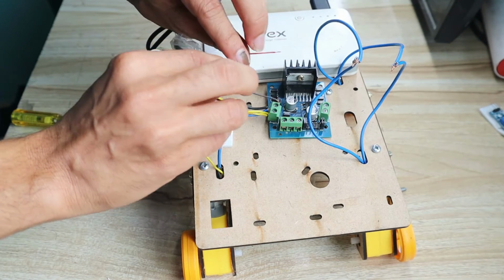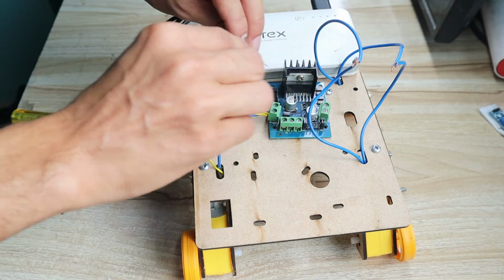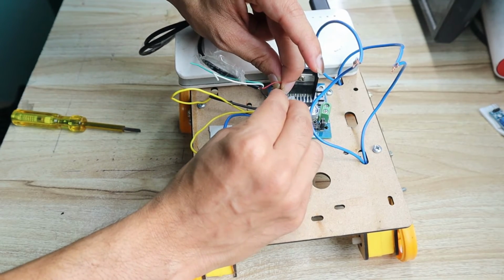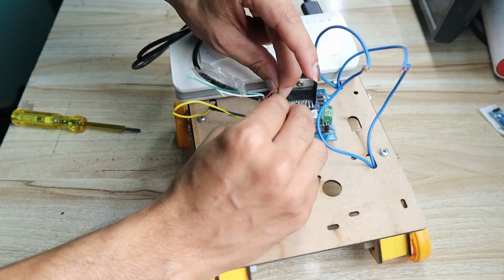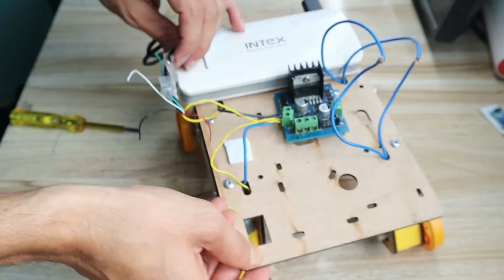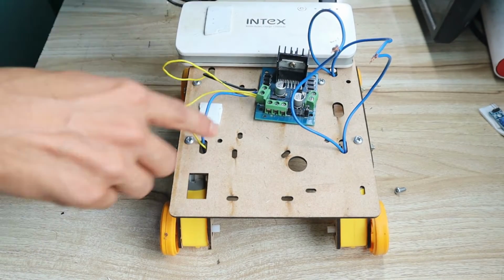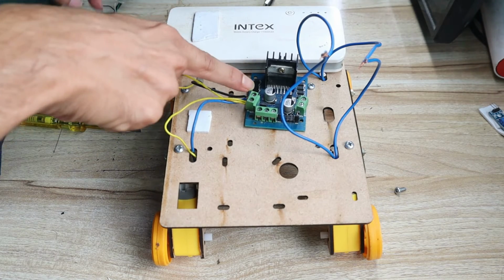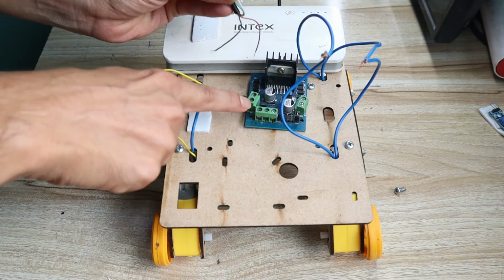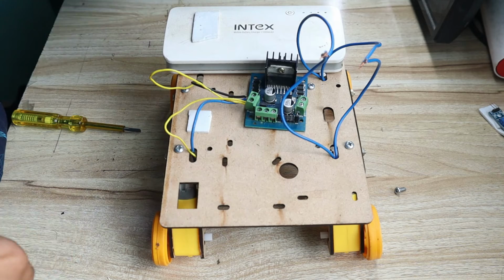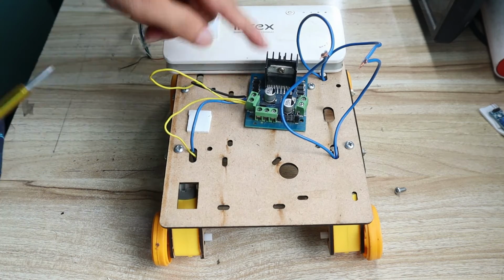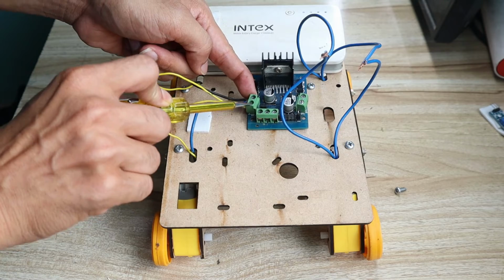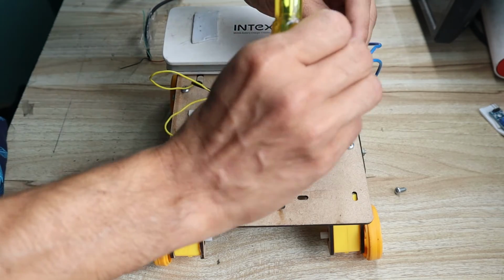Okay, you can give the positive, negative pin and just check which direction your motor is rotating. Your two motors should be rotated in the same direction. Now I can see my motor rotating in the same direction, that is the clockwise direction. Okay, so this is done. Here I connected the positive pin, here I connected the negative pin. Just focus on that one. So this pin we have connected positive, this pin we have connected negative. That is very important, we require it later.